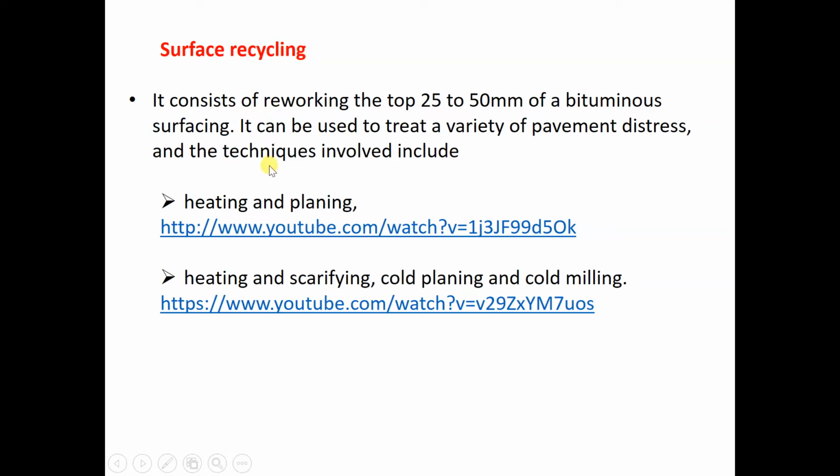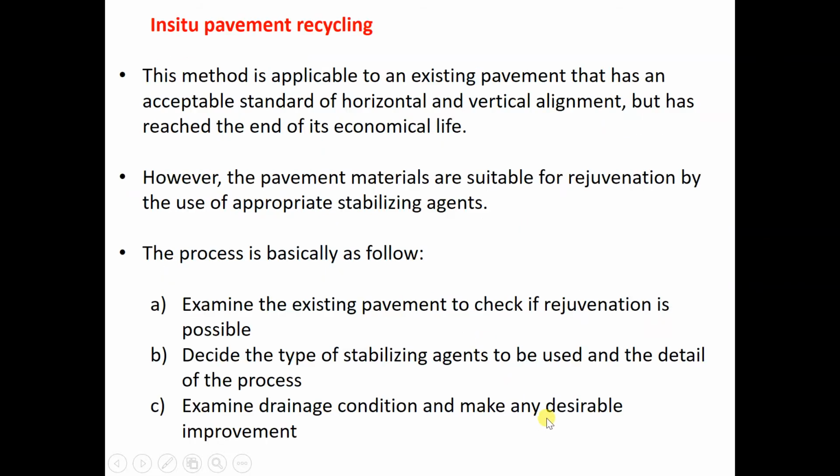Second one is the planing. All the old asphalt is planed off, put on trucks, brought somewhere else and then rejuvenated. They add some new asphalt, add some bitumen, and then bring it in. It's a reuse of the aggregates inside. The bitumen is reused as well, because bitumen you can rejuvenate. You might have to reheat it, and you add some more new bitumen to it. Okay.